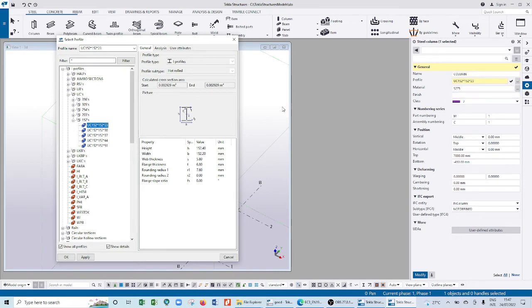Okay, in the interest of time, I'll just pick that column, only one column, and put the base. Then I'll go for your beam, connect the beam to a column and do the base, then run the drawing. Then you will do the same thing. So get this concept and follow it for all of them. So you choose this. We have a 152 by 152 by 23. Are we there? Click on it, press apply, press OK.